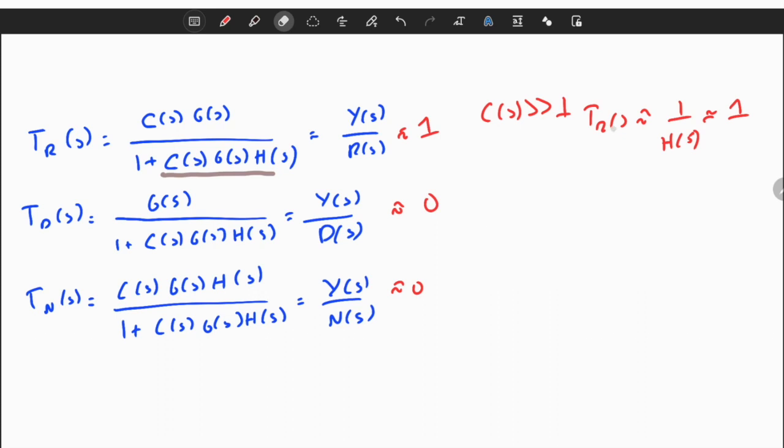From this perspective, we know that for a good control system, for good tracking performance, we need a high gain feedback controller. We want an aggressive feedback controller. So this is the story. What is high gain? It depends on your controller and on your system performance. It can be just a constant, or it can be some sort of periodic controller. The definition of high gain can depend on S and on the frequency response. But this is the idea.